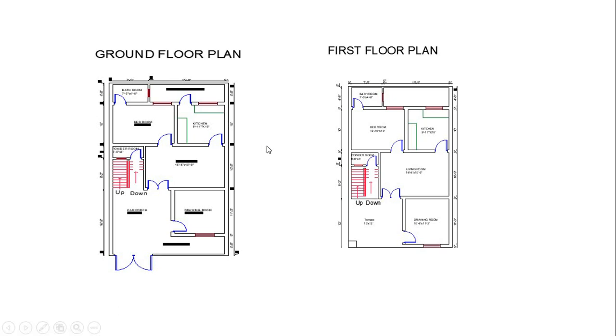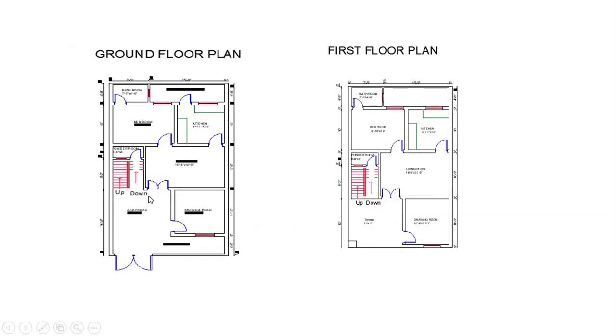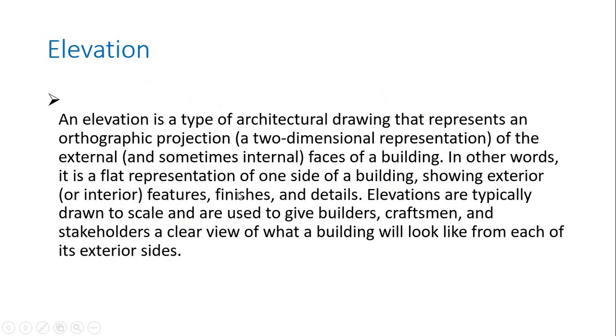So again we're going ahead like that. Now we are concerned with elevation. As you can see, if we go back to the previous one, the doors should not be planned like this. From here to here, these are parallel doors. If a man is standing here and these 2 doors are open, he can directly see into our bedroom. So this is a wrong placement of a door. You cannot place the door in this way. And now we're going ahead.